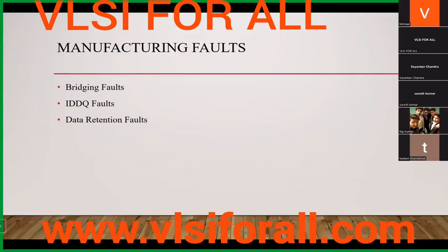It's actually memory. When we program our memories, but after some time the data gets dissolved, or we can say the data is not retained in that cell. That is what we call a data retention fault. It is not able to retain the data which we have already programmed in the memory. And what are coupling faults? Anyone have any idea? These are all memory faults we are talking about.